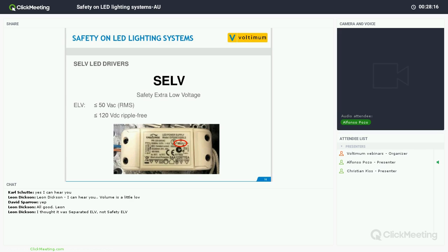Also, apart from ELV, extra low voltage, just safe isolation in these products refers to the isolation between the primary circuit, which is basically AC mains, and the secondary side, which is the output voltage. For example, it can be used in an isolation transformer. The secondary circuit has no direct connection with the primary side, and under any faulty condition, it derives its power via the isolation transformer, converter, or any equivalent protection system that it might have.